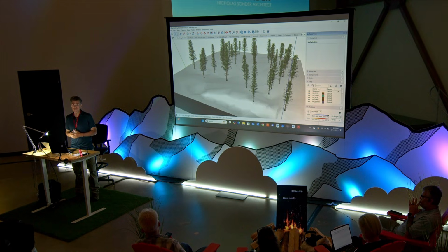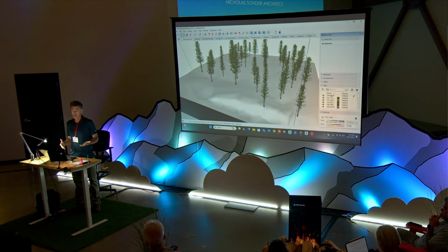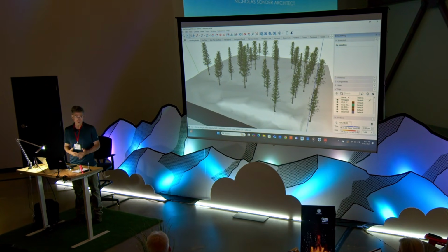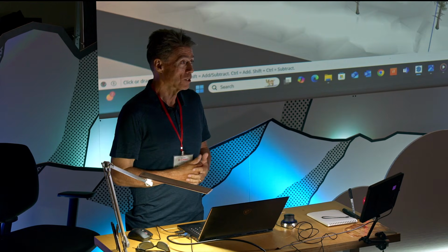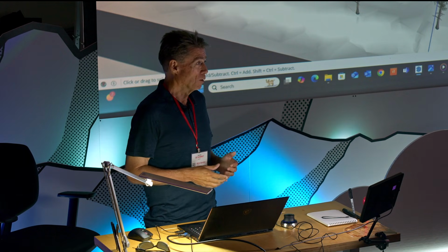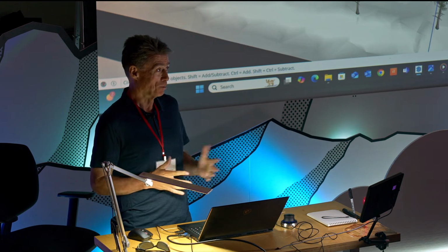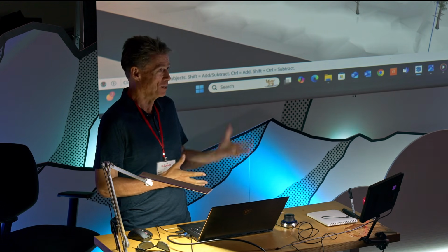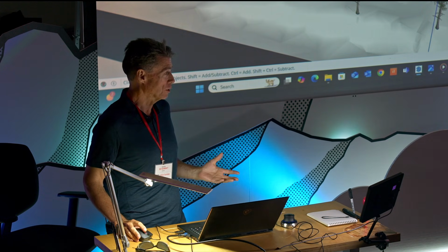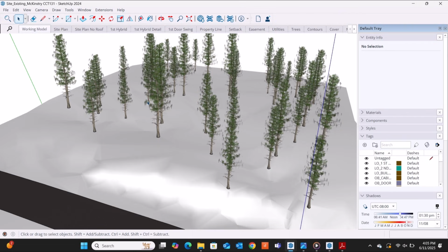All of that, but it does have its implications on home design that you don't necessarily deal with in any other regions that don't deal with heavy snow, because it's also not just light, dry snow like you get in Colorado. Like I designed a house in Crested Butte, and I was amazed that their snow load was only 90 pounds per square foot, where we have snow loads that go up to 500, 600 pounds per square foot. To put that in perspective, that's like planting Humvees on end on your roof. So it creates some very deep structure all the way down through to the foundation. But we've only got an hour, so I'm going to try and go through some of this quickly.